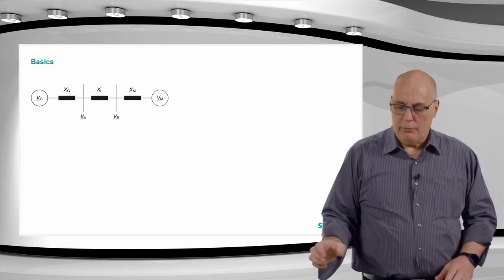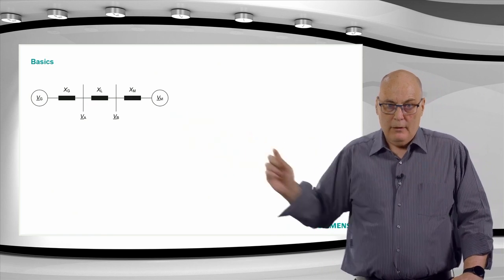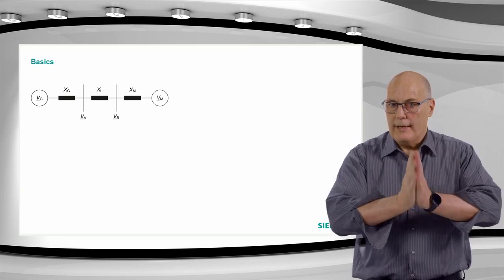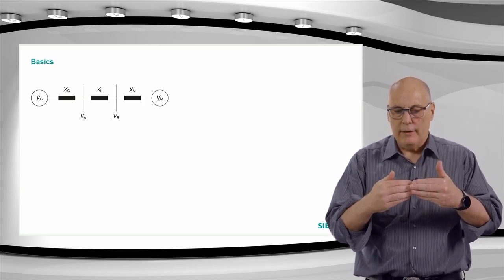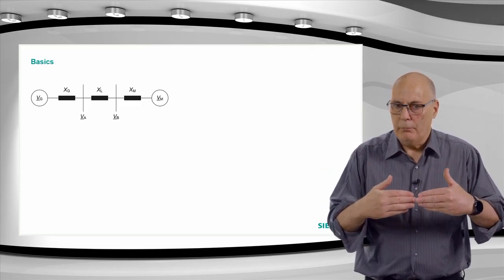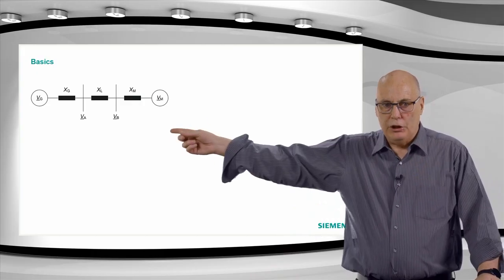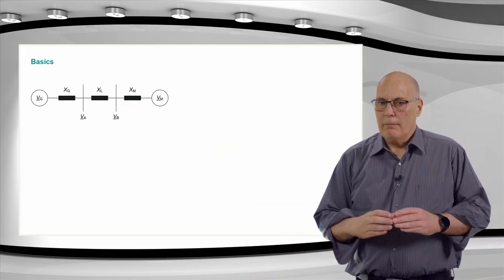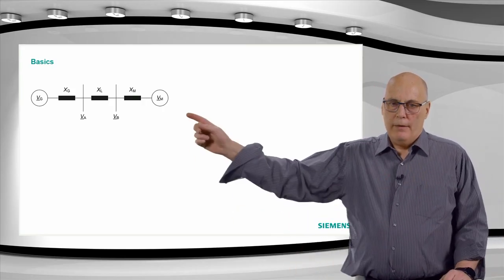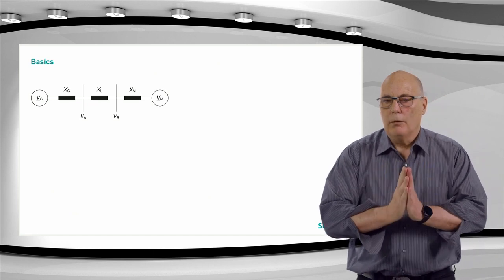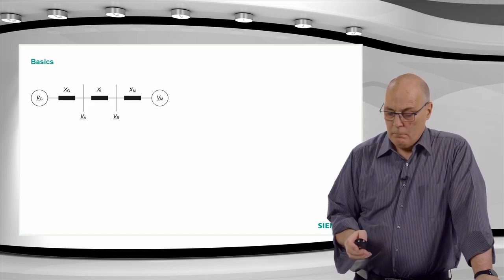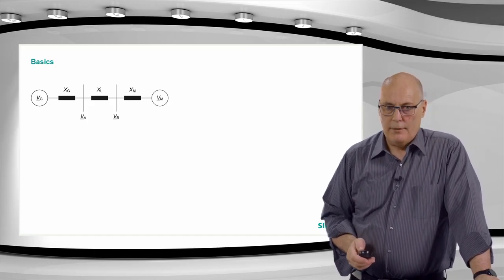If you place a relay at the bus A over here, that relay with its current and voltage measurement will look forward towards the XL, and whatever that relay would see, a short circuit in front of it, would be defined by the source impedance. That source impedance is all the generation behind it. That would be the VG and XG, our one equivalent source. You can reduce the entire source of that one relay to one equivalent generation. And the same in front of it, you can have the ZL and the remote bus bar, one equivalent load. So the two-machine model is very, very effective in analyzing and modeling the power system.